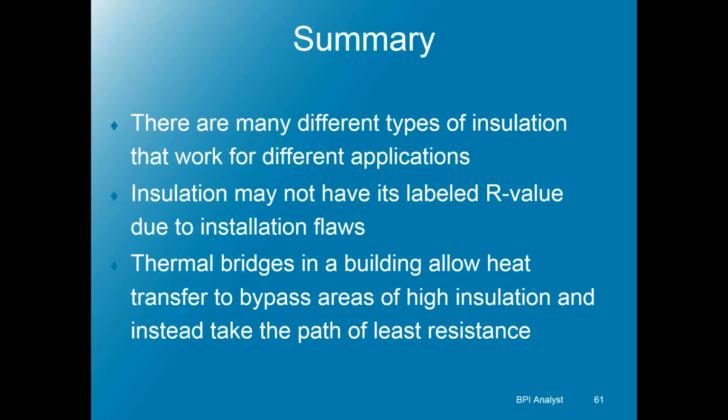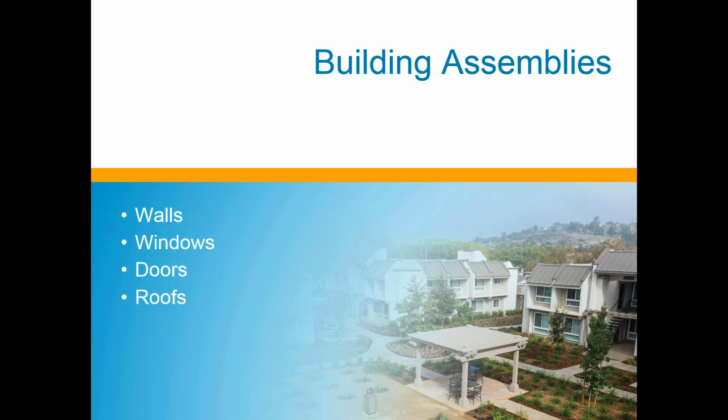So, summary: a bunch of different insulation types. Polystyrene, polyisocyanurate, extruded polystyrene, expanded polystyrene, lots of different insulation types. Being able to identify at least fiberglass from cellulose is important. I think most foams you're going to know if it's a foam. So if you can identify foam from cellulose from fiberglass, that's important, and that's usually what you're going to see. And then thermal bridging, hopefully.